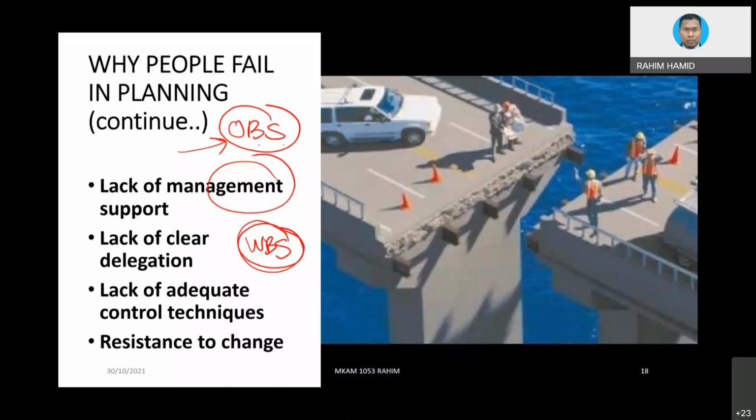First thing first, what we are going to do. In construction, for instance, we are going to put, for example, the site preparation, the groundwork. Site preparation has many sub-activities. Then we move on into substructure works, meaning work below ground, such as piling, basement if there are basements, ground beam, etc. Then superstructure.